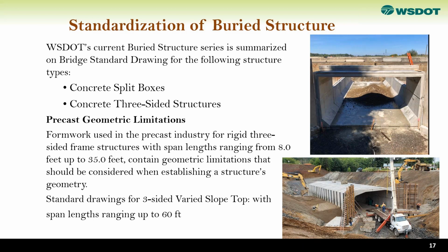The span range for the precast concrete in the standard plan that we are doing is 8 to 35 feet. Conventionally, for bridges, anything related to the bridge office is 20 feet and above. But because of the NBI requirement, and for our practice of fish passage, we go with whatever is covered, which is way below 20 feet. We are covering 8 to 35 feet for a standard drawing, but we also have standard drawings up to 60 feet in place and in use in the office.